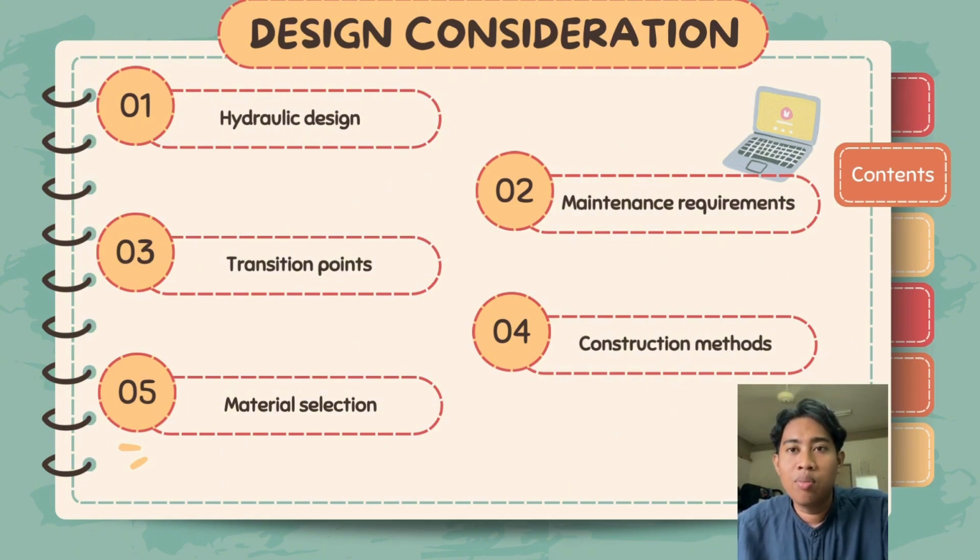It is to ensure spoil does not obstruct runoff flow. Fifth is material selection. Choose material resistant to harsh weather and chemical exposure. Preferably precast concrete for long-term durability.